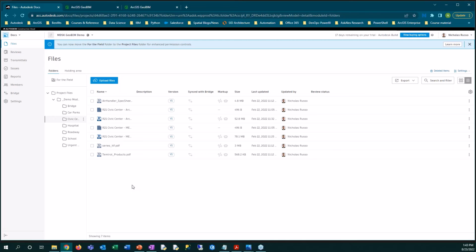And one thing to note is you can use an Esri CAD PRJ naming convention. So if I named this as esricad.prj, we could get rid of all of the other PRJ files within this file directory. And when they're brought into ArcGIS Pro, they would all read off of the same projection document.